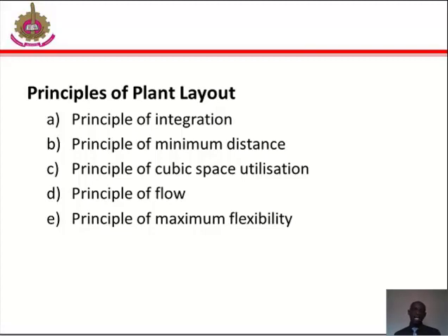Principle of integration. A good layout is one that integrates men, materials, machines, and supporting services in order to get the optimum utilization of resources and maximum effectiveness. Under principle of minimum distance, the principle is concerned with the minimum travel or movement of men and materials. The facilities should be arranged such that total distance traveled by the men and materials should be minimum, and as far as possible, straight line movement should be preferred.